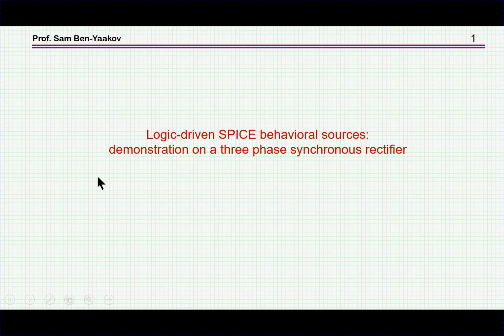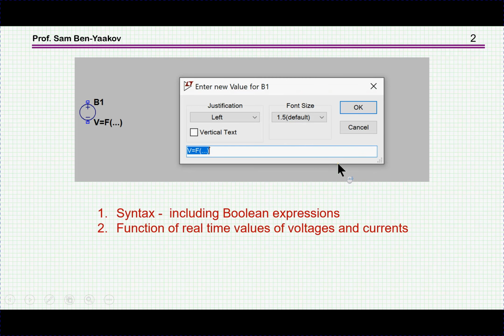Hi, I'm Ben-Yaakov. This presentation is entitled Logic-Driven Spice Behavioral Sources and a demonstration on a three-phase synchronous rectifier. Now, Spice has dependent sources or behavioral sources, which come in different forms in the different packages.